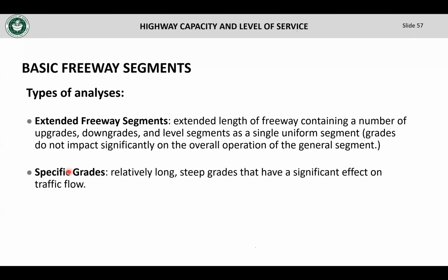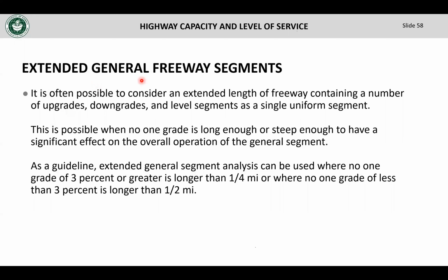Or, when you have a significant impact of grades, when you have relatively long steep grades that have a significant effect on traffic flow, you will do a specific grade analysis. So for the general freeway segments, you have grades that do not significantly affect the performance of the freeway, like an upgrade followed by a downgrade. They're all relatively small, short enough that they don't affect the speed.